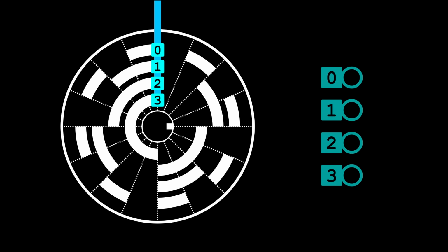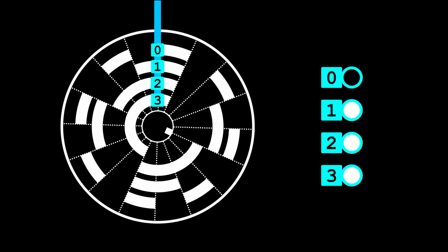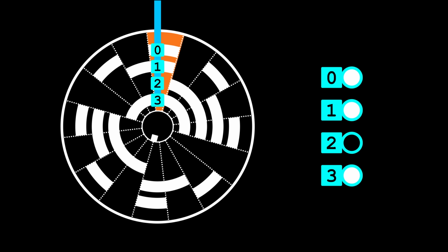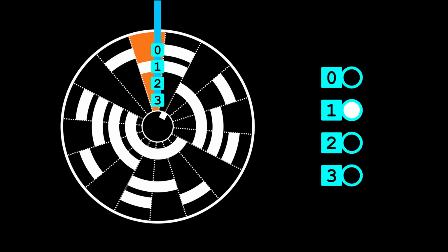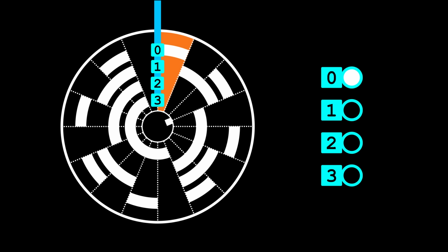A simple binary encoding will give a unique 4-bit value for each of the 16 sectors, so we'll always be able to know which sector we're in based on that value. And that works fine, except what happens when an encoder happens to be positioned directly above a transition from light to dark, so that half of its field is white and half is black? Its reading will be indeterminate, giving either a 1 or a 0 depending on the lighting and how clean the disk is and 1,000 other things.